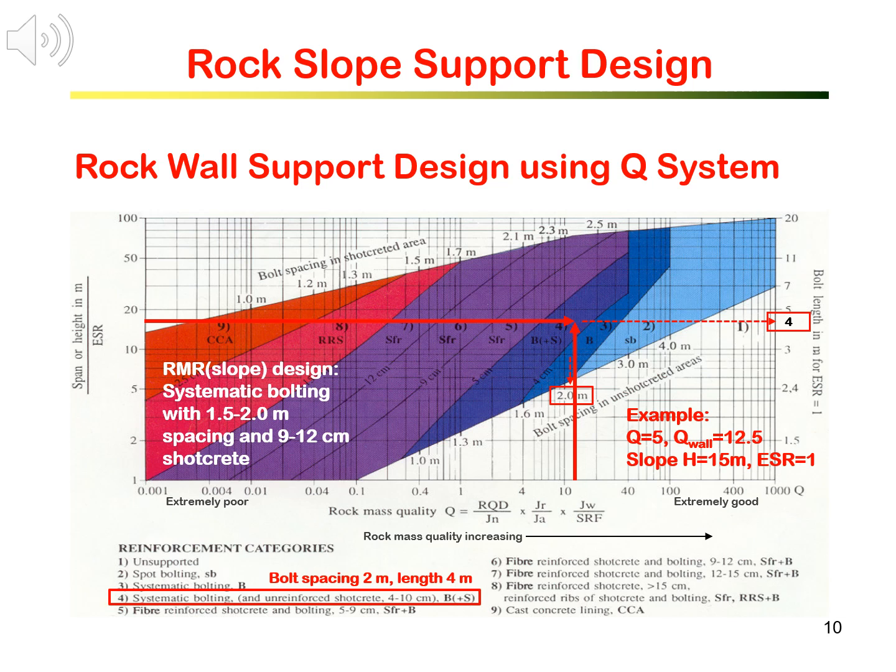Please note both IMR and the Q systems are estimating the rock mass quality. The approaches using IMR and Q are empirical. Nevertheless, they, particularly the IMR slope, provide a systematic and quantitative method allowing us to assess the rock slope stability and to design rock slope support.